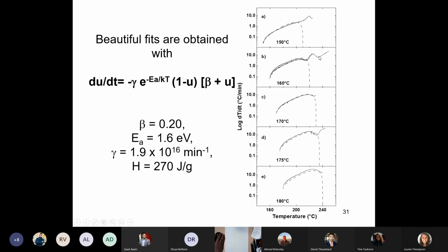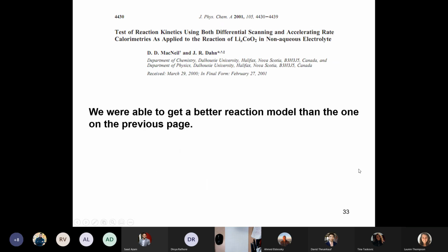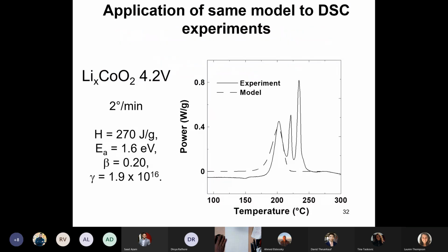And then you run over this peak and you quench the sample, you air cool very rapidly, and you take X-ray diffraction. And then you let it go to completion and you measure X-ray diffraction. And that's how you figure out what's going on. Alternatively, you could stop the DSC at this point, or at this point, or at this point, and examine the sample and see what's going on.